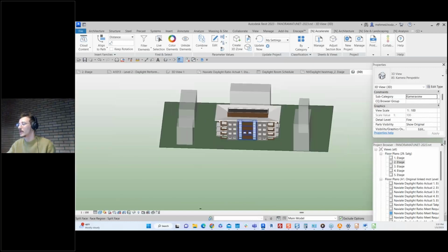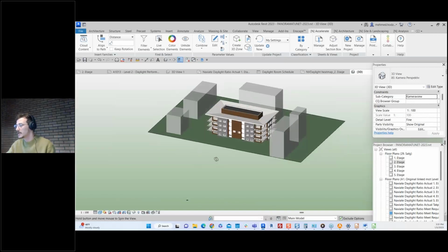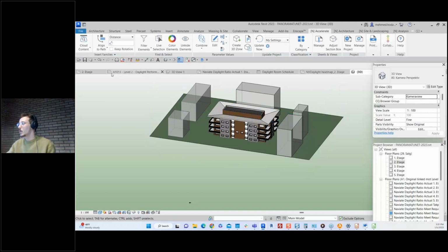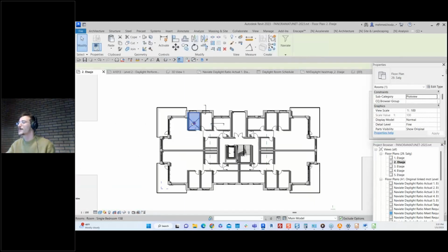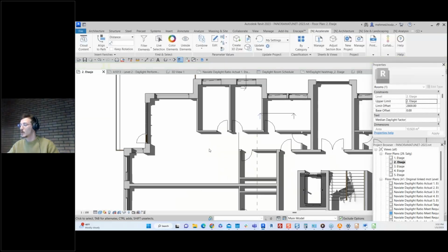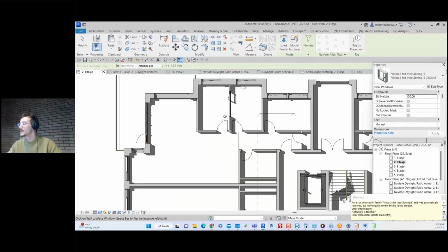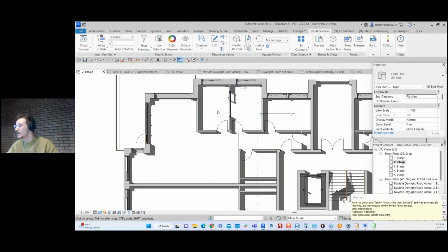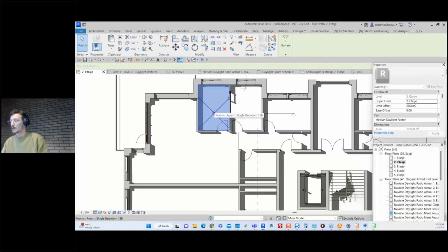What we do when it comes to daylight factor, we basically send the complete model. So let's say if this is the model, these are the linked elements, and when you, for example, calculate just for one room, if you calculate the daylight performance, we will send the complete model to Radiance. That's the calculation engine that's used for these kind of simulations. We'll send the complete model, and that will include, for example, a window that's found in between two rooms. So we will include that also in the calculation, of course. So no consideration is to be taken with it. It's included in that sense.